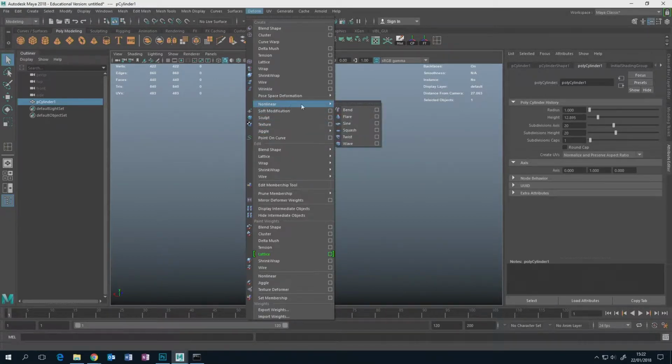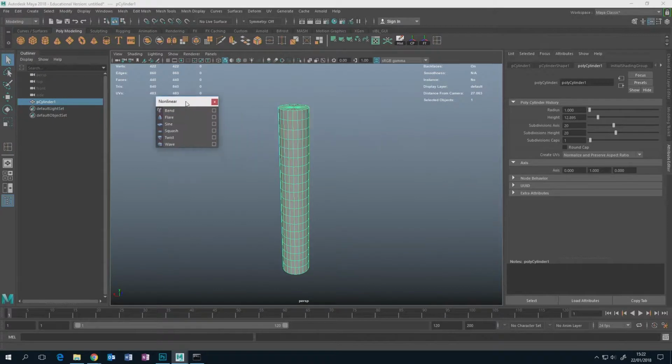Sometimes, if you move an object away from the origin and you want it back at the middle, you know that you can make that 0, 0, 0 like that. Sometimes you want to sort of resettle this to 0. Maybe you've moved this off and you want this to be the 0, 0, 0 point. You don't want the center point to be the 0, 0, 0 point.